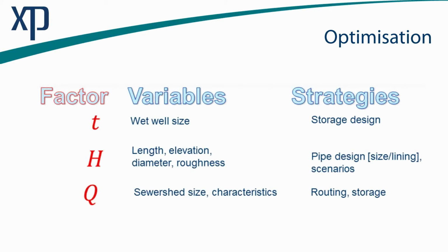So friction does play a very, very important part of your rising mains, as well as the actual pump itself. So rising main design: what kind of material is your rising main going to be made out of? How resilient is it to the pumped head? Do you have cyclic issues inside that rising main? Will that rising main last or resist the number of pump cycles over a 50 or 100-year design life? Hoop stress scenarios, all of those key elements to a pipeline design should be analysed.